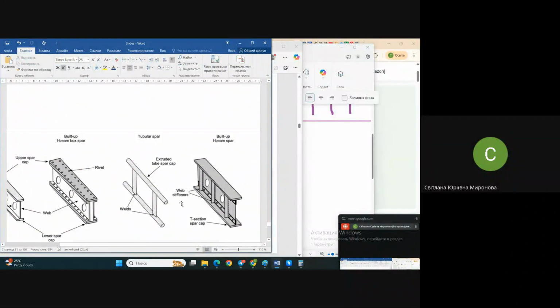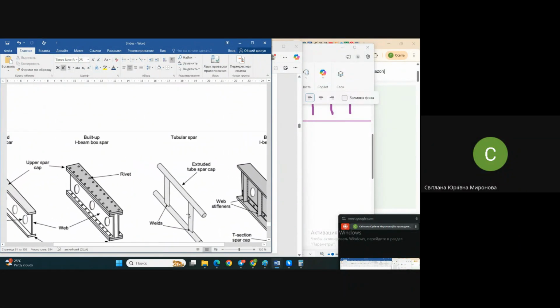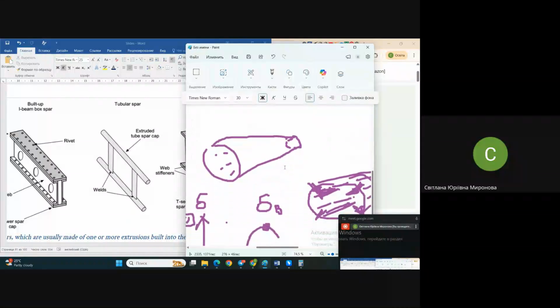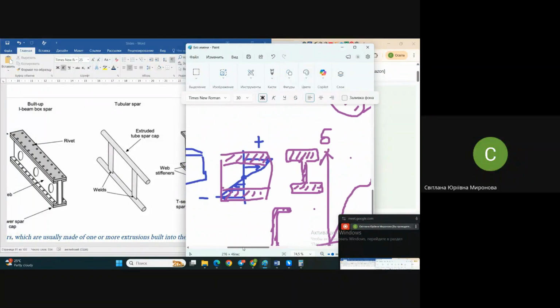Struts or stiffeners, what you see here right now. I hope you understand, these stiffeners are necessary to join ribs. One of their functions, additionally, is that you might join ribs with the help of those stiffeners, and also join the ribs to the web. The real function of these stiffeners is exactly to make the web stiffer, to add stiffness. Once again, the same strength, like what I tried to explain here.